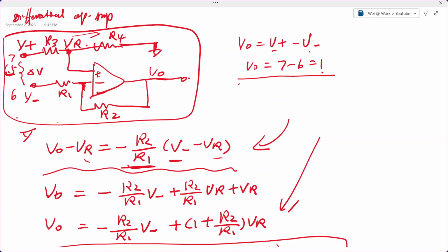So it's only the difference, no common mode voltage. That's a very typical way to remove common mode voltage. Then if you remove the common mode voltage and only keep the difference voltage, you can level shift to any voltage you want to interface with the ADC or whatever other applications you want.